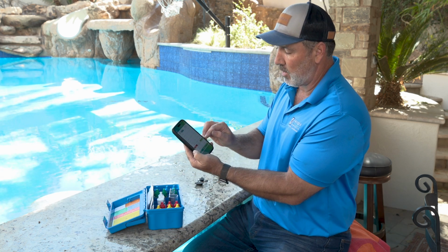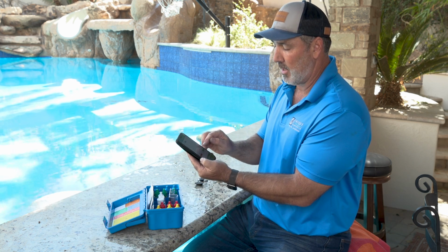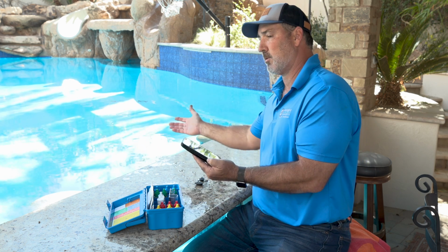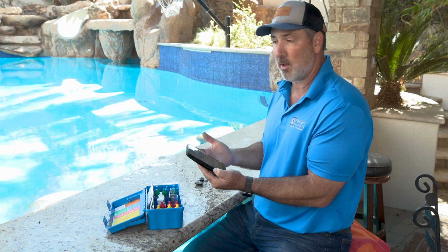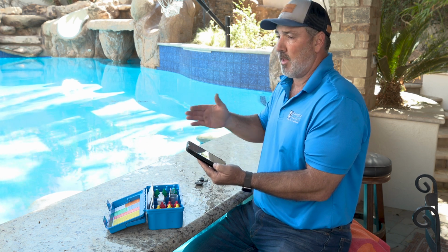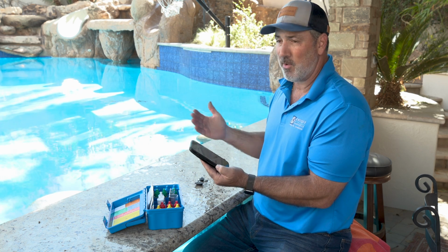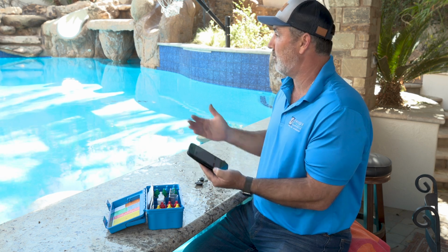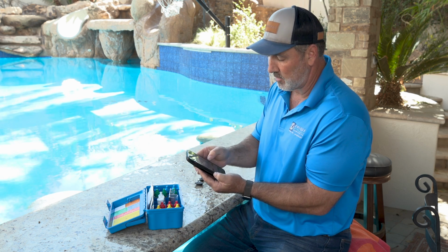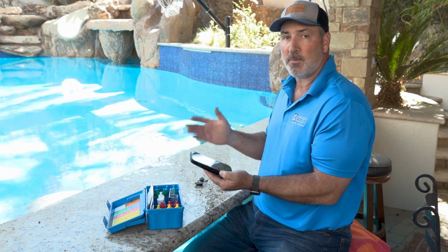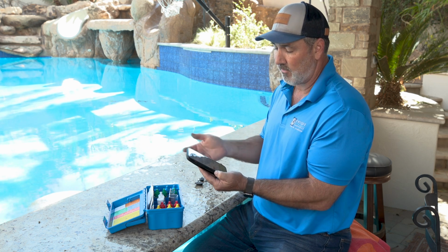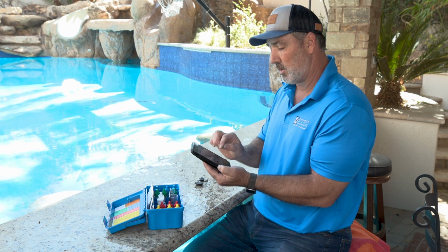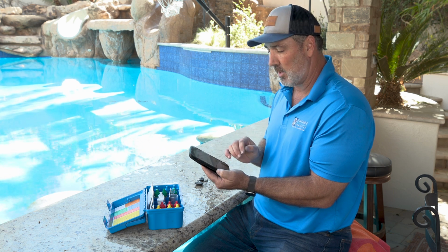So this is the number that you want to see. You want to see the green in the LSI. Again, calcium, you're not going to change. We'll start up your pool with 250 to 300 parts per million of calcium. You're going to see that number slowly go up over time, but you don't need to add calcium or remove calcium. In fact, the only way to remove calcium is to drain your pool, or partial drains of the pool. Cyanuric you might want to play with. So cyanuric can affect the LSI, but for the most part, your pH and your alkalinity is what really drives that LSI number, and that's what you need to keep track of.